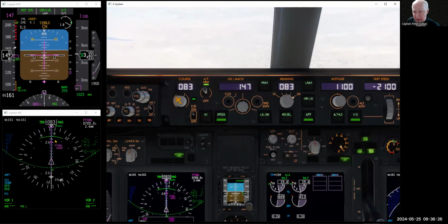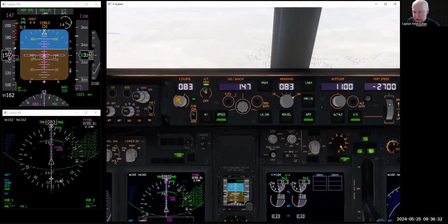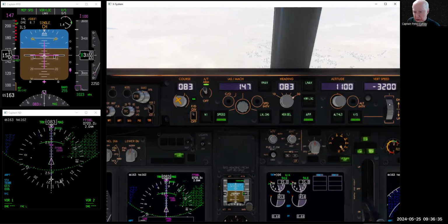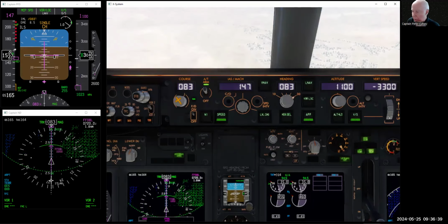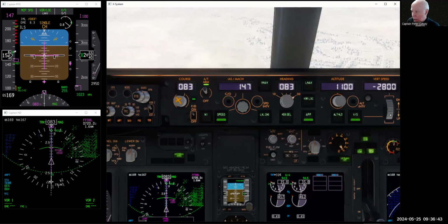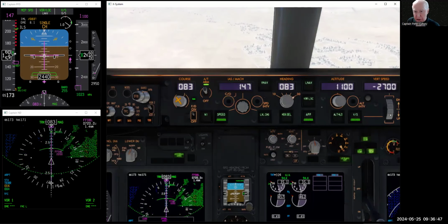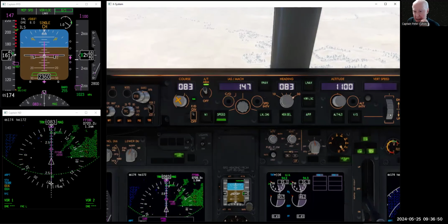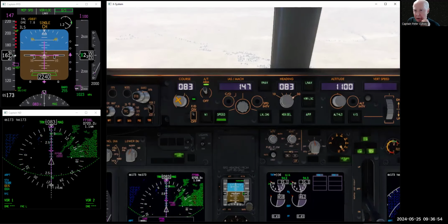So let's continue that vertical speed so we can see where it is on the nav display. There it is on the nav display now, and we've got to have it so that we are in a position that at our current speed, we can intercept the glide slope from above. So I'm having to cheat a little bit here just to do that. We're stable, we're looking good. So we've increased it, radio altimeter alive, we've got that, and landing check to go yet. So we're on the glide slope.